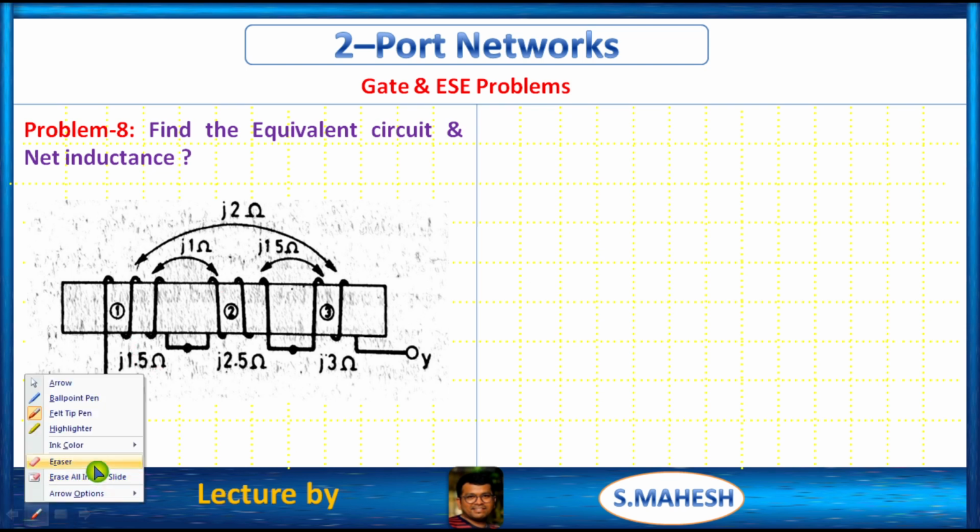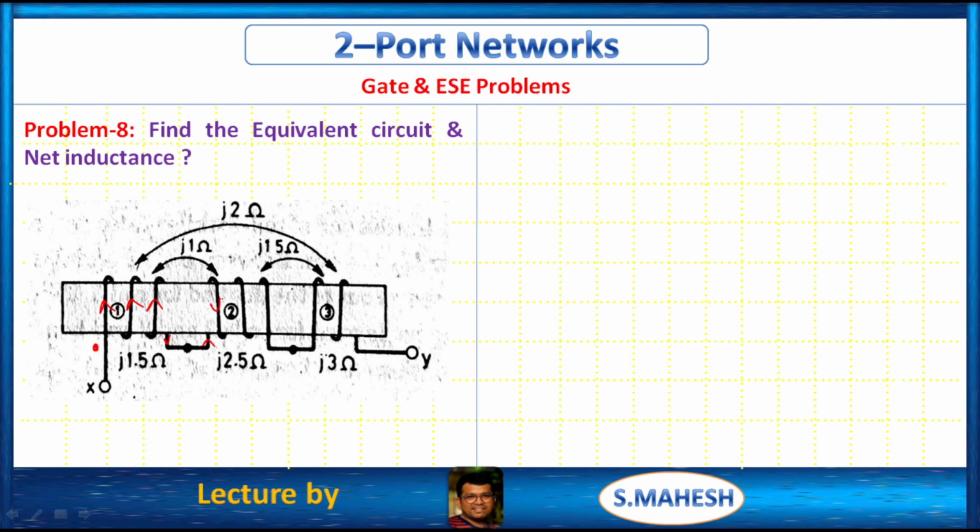See, this is a very important observation. Here the sense of winding is starting from here, right? For example, this is the dot, current enters, this is leaving, again it enters. Now the sense of winding changes. Enters, now leaves. So from this dot current enters, but from this, because of the sense of winding, the current leaves. See, the current leaves from this dot.